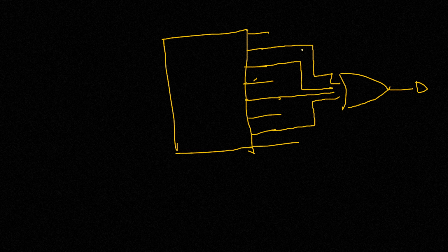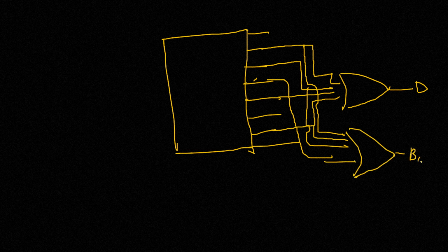This was D. And then we have 1, 2, 3, and 7 for borrow. Right. So this is how we've used a 1:8 demux for the subtractor, where A, B, and C are used as the select lines. Like you can see, the circuit has become much simpler, where you've just used 1 demux and 2 OR gates. So that is the application of demux.